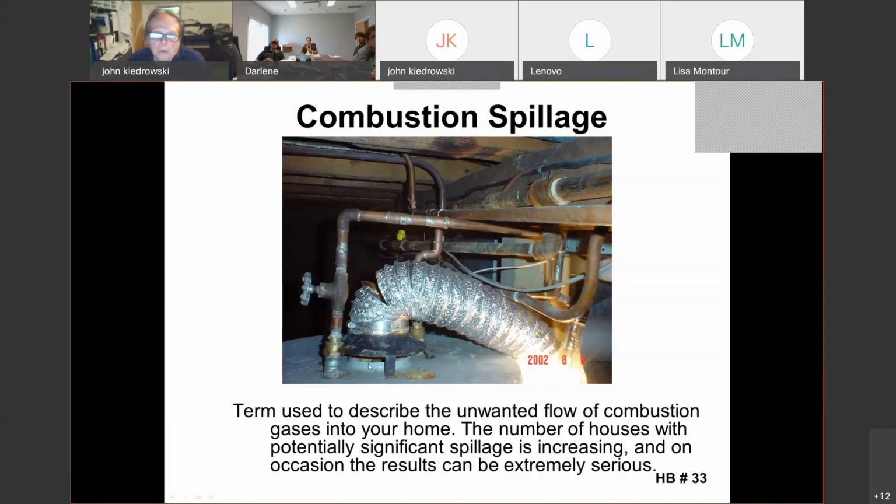So it's an old water heater, and we see this exhaust system where it would be pulling the air, if you follow my arrow, up and through, and it should be solid duct, not a coiled duct. Number one, this is a dryer vent that was never intended for this type of application. Of course, I can see why they did it, because everything's in the way. In fact, there's a light right there too that's hanging down.